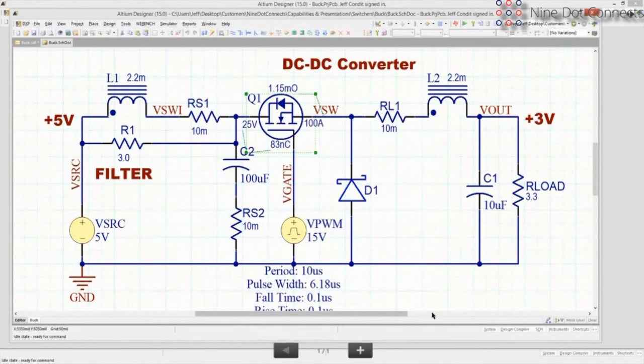The problem is that there's another set of harmonics that's even more critical, and that has to do with the slope of the rising edge. If you have a single edge all by itself that goes from low to high, but it's going to go from low to high very quickly, then it's going to take a lot of high-frequency energy to make that transition occur. If you were to look at that and decompose it, you would find out that it has to do with the slope of that curve.